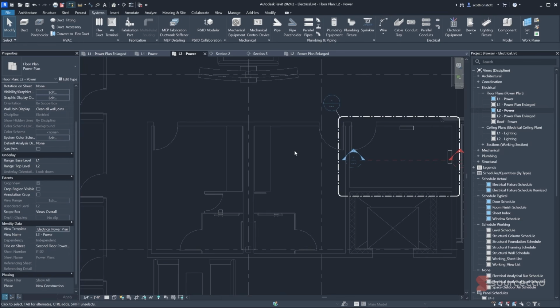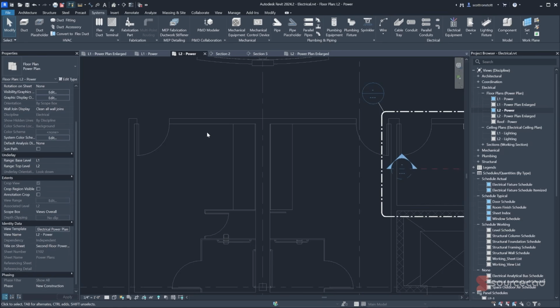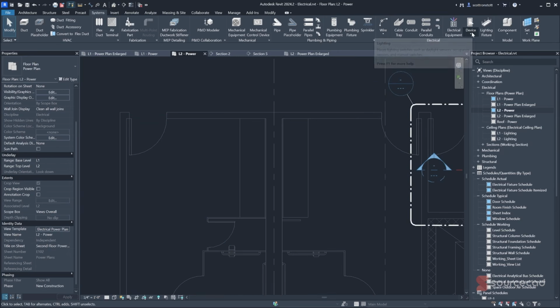And for electrical power in here, we really only need, maybe we need something for, it depends on if we have a hot air hand drying solution on the wall over here. And we might want to have a GFI plug on the wall over here. So let's just plan to put 2 GFIs in each restroom.